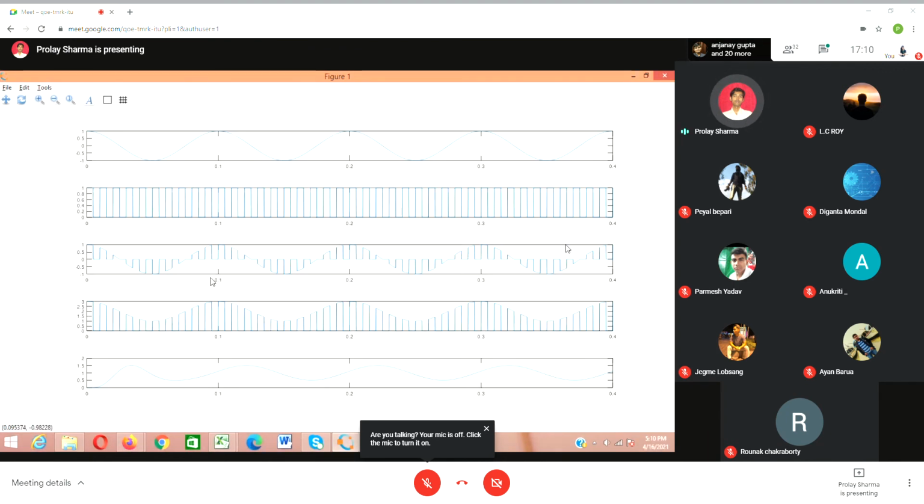Obviously, there will be a time delay. As you know, you have seen the phase response of the filter. There is some phase difference, so that's why there is a phase delay with this reconstructed segment. That can be explained from the phase response of the Butterworth filter. Just in the last program, we have seen that there is a considerable amount of phase difference there. That's why this small amount of delay is coming. So this is the output of application of the low pass filter.